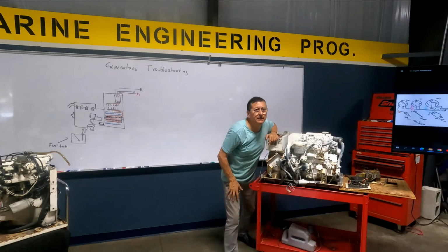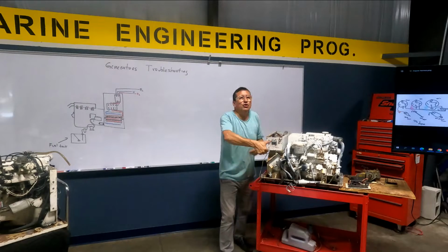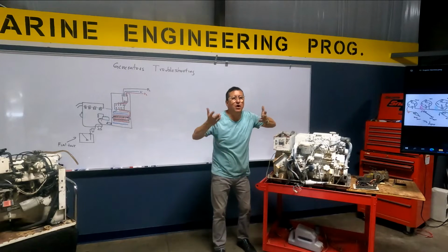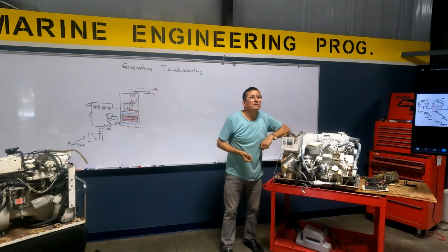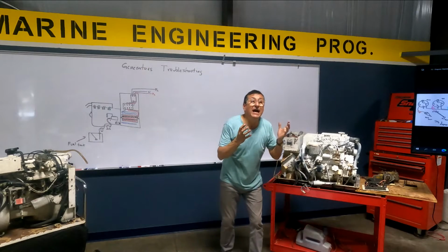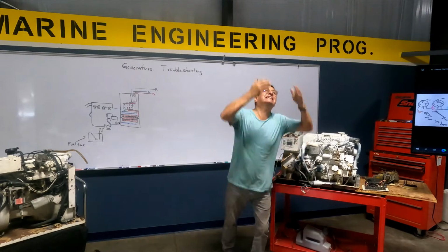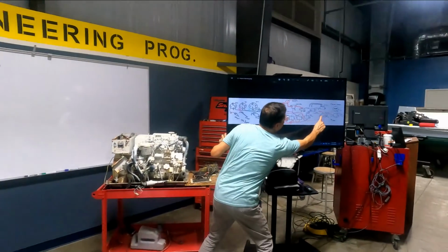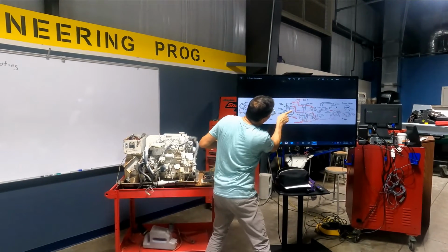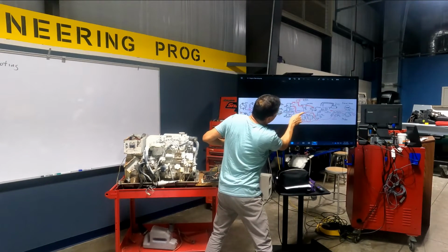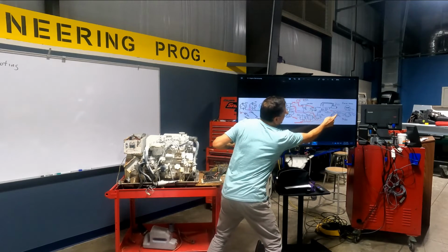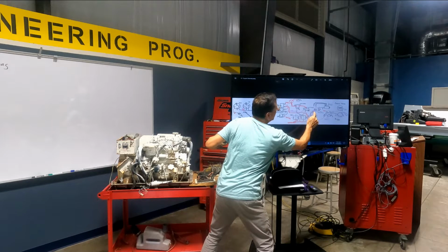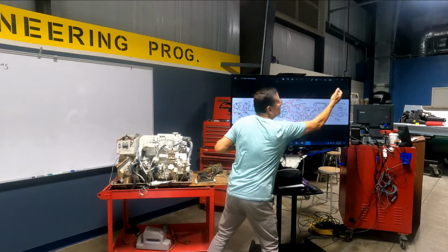You understand? How can you eliminate that? Or do you need to stay with the preheat for 10 hours? No, you need to go drive the boat, no? I remember that you hold it for like 10 seconds, until what? Until the alternator sends the power. You remember that cable with a diode here? Look, this is the purple cable from preheat. So when you remove your finger here, it's because the alternator is sending power here, and the power continues to the fuel pump, solenoid, and so on.